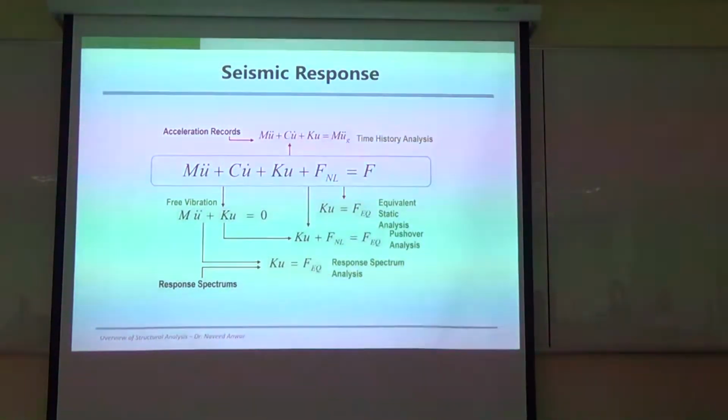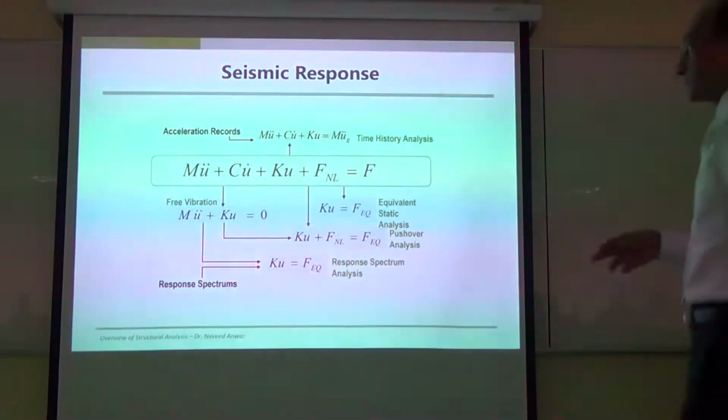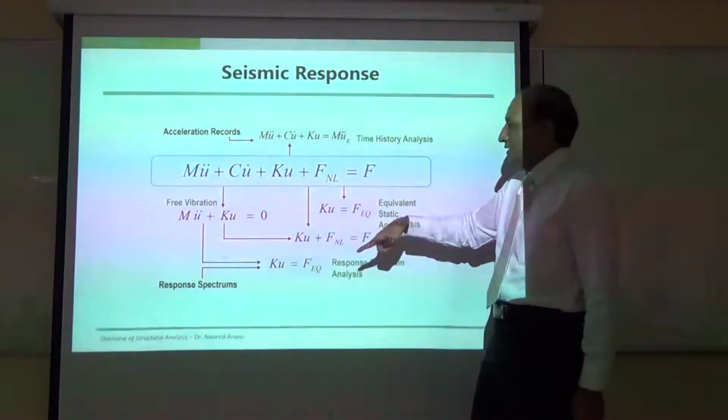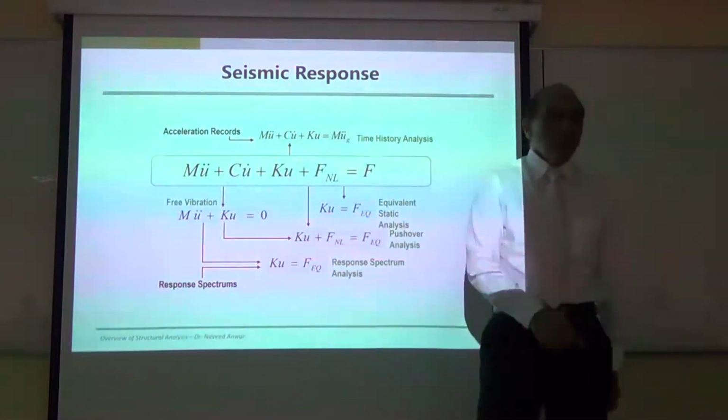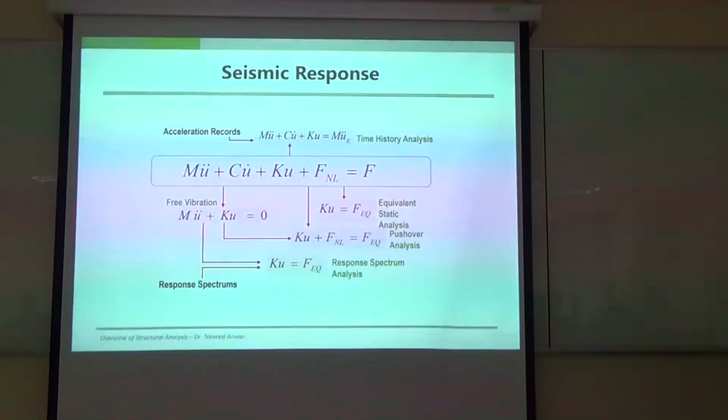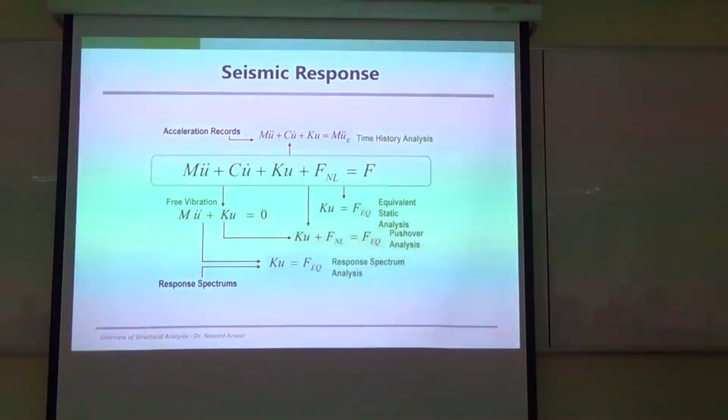At least 10 times more work in terms of the effort. But in a design office like ours, we normally do most of them, not only one. We use all of them for different purposes. We always do a static equivalent also. We always do response spectrum also. We also do linear dynamic analysis. And we also do a nonlinear. Sometimes we also do pushover.